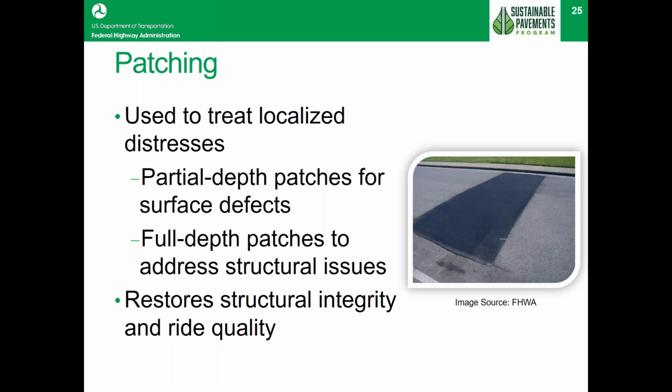The second item, taking one step up the ladder, is getting into patching on asphalt pavements. Frequently, this is done just prior to doing some kind of a larger preservation activity. For example, you might do a patch and then apply a microsurfacing over it. So a lot of times this is something you might have to do where most of the pavement's in pretty good shape, but you have just some selected areas that have deteriorated for one reason or another.